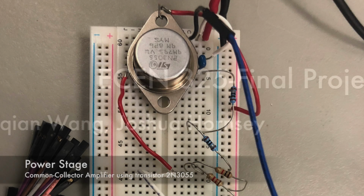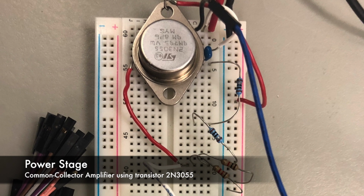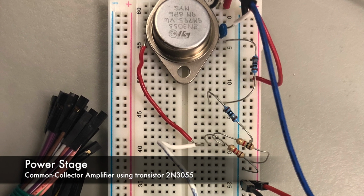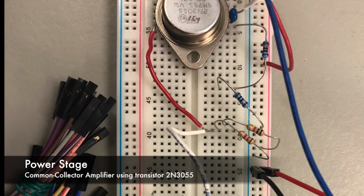Our design begins with the last stage, which is the power stage. We use a common collector amplifier to achieve a gain of nearly unity. Since we know the maximum input and overall gain requirement, we can easily calculate the maximum output swing and start from there.